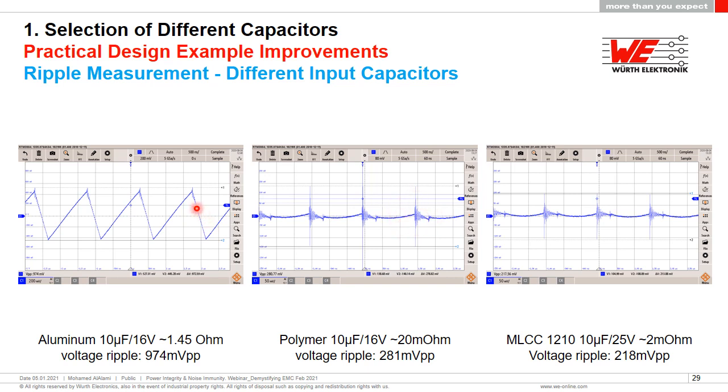So that's still here. It's just you can't see it because of the larger ripple associated with the ESR. That's taken over this, so that's basically doing this. So this is swamped by this high frequency noise.